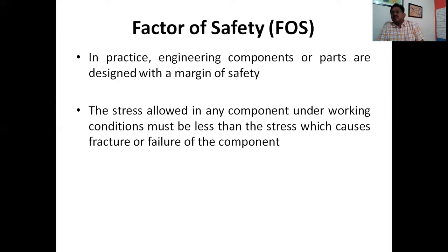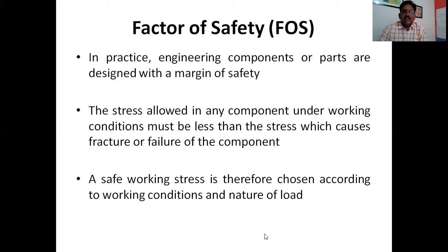Therefore, this is because the safety and working of the components are very important. So the stress allowed in any component under working condition must be less than the stress which causes a fracture or failure of the component. Therefore, a safe working stress is chosen according to the working condition and the nature of the load.